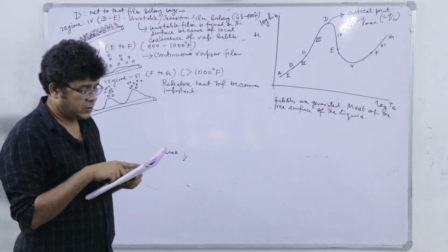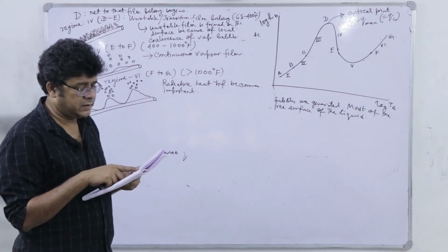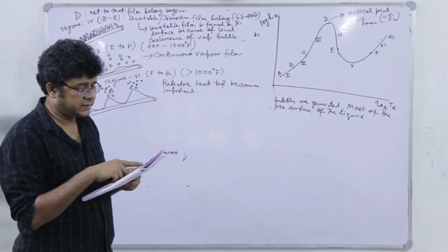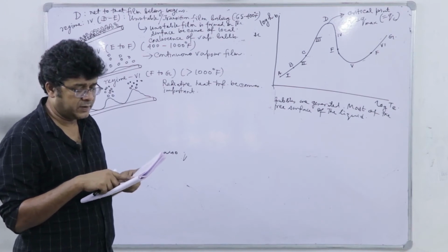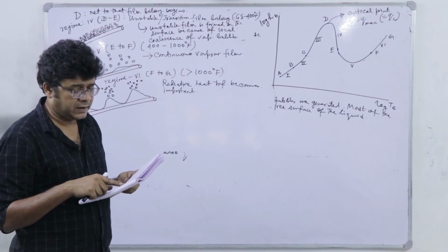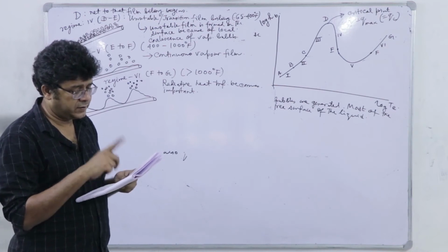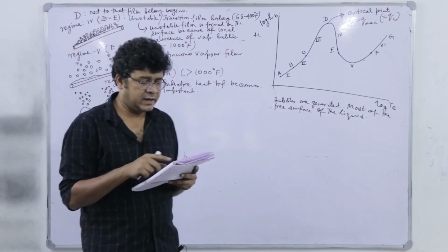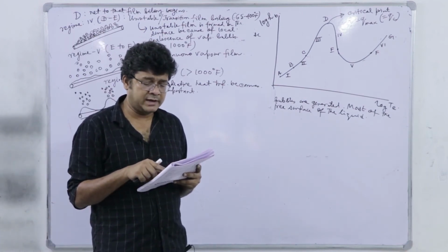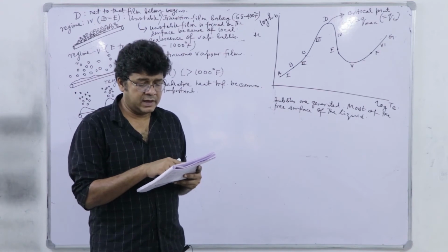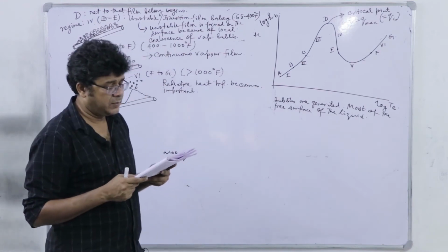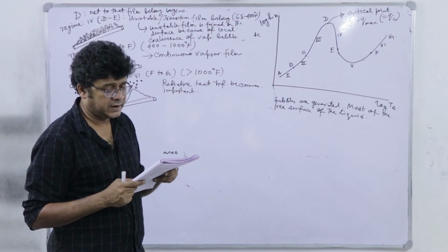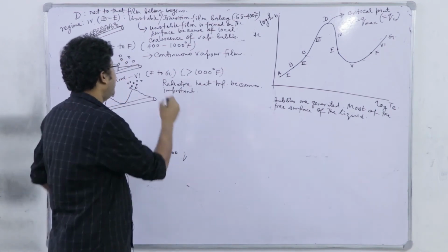Like, what are the features? Where temperature increases so much, the radiative heat transfer becomes important. The characteristic of this regime F to G, that is the regime 6, these are the fundamental characteristics, and if the excess temperature is too high, the heating wire may even melt. The melting or burnout of the heat transfer surface is sometimes called boiling crisis.